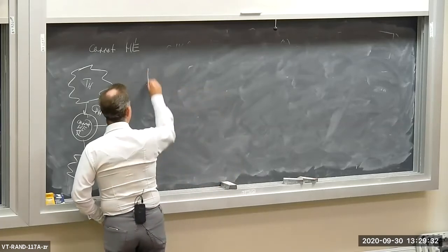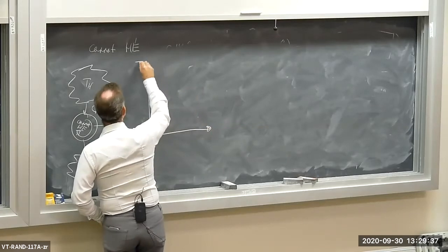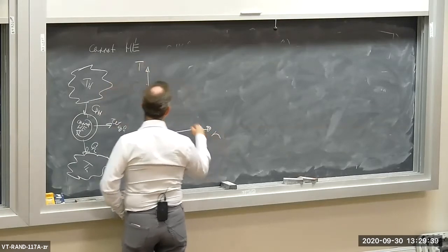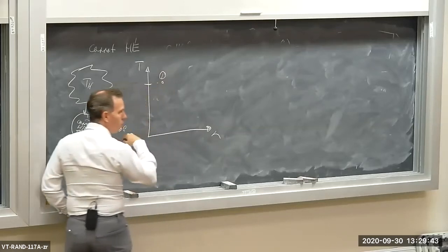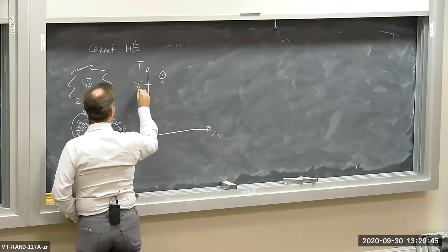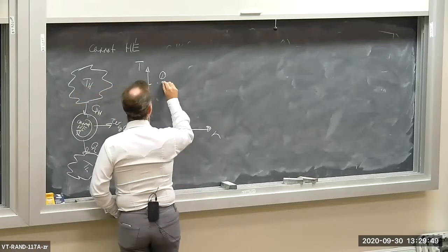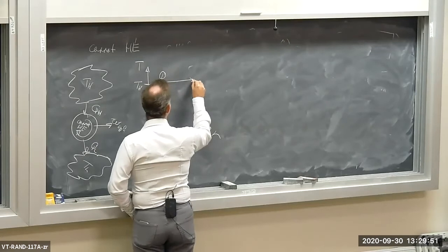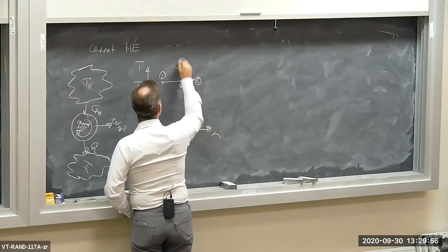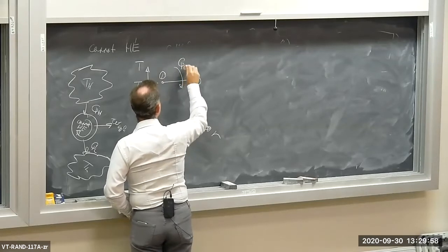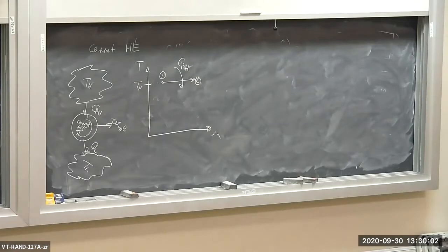The TV diagram, as you recall, for the Carnot cycle. We start at state 1, which is the working fluid at a temperature T high, at the minimum volume, and then we expand it to state 2 isothermally. This is where the heat transfer is being performed from the high temperature reservoir at TH.